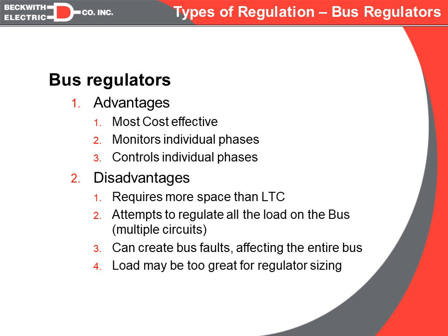Typically this would be done with 3 single phases, so that gives it an advantage also that we're now monitoring each phase individually and we can control each phase individually. So unlike an LTC, we do not have to be balanced between the 3 phases at the bus level in order to apply bus regulators.